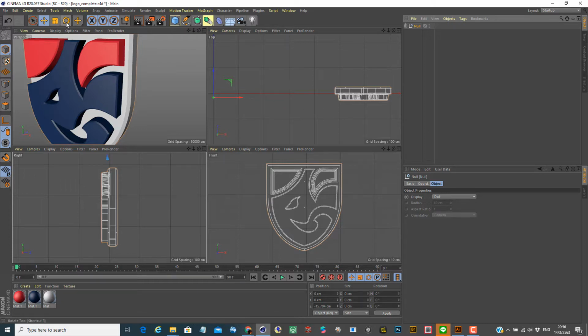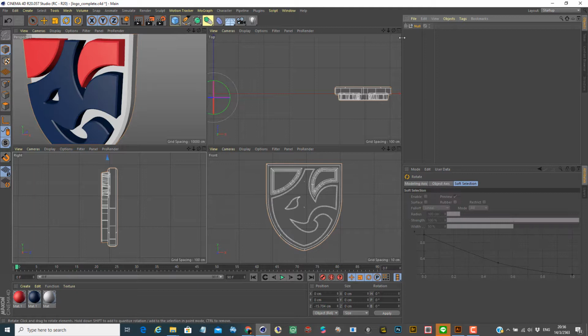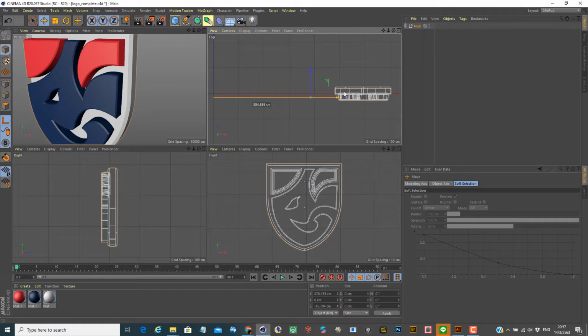The problem right now is, if I try to rotate this thing, you see what happened? If I try to rotate my objects, it's going to rotate on the registration point, not along with the logo itself. So that's why I need to move this registration point from here to the logo. How are we going to do that? We have to move to the orientation tool, this one. When you roll over, you can see enable axis. You can click on that, or the shortcut is L, and then you will be able to move it. Right now I just move it to align with the logo.